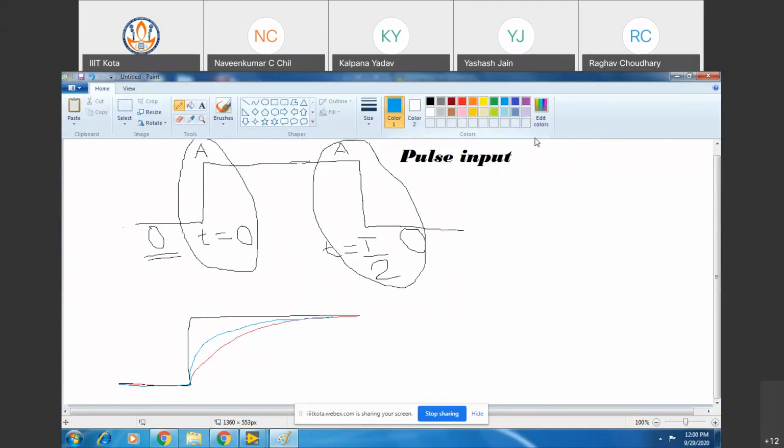Have you seen the discrete plot of the Fourier series sometime? Have you plotted that at different frequencies, omega, 2 omega, 3 omega? You had discrete vertical lines. Yes, you remember those plots? A naught was what? That was the DC value, and the An and Bn were the coefficients of sinusoids. So An was associated with cos and Bn was associated with sine.